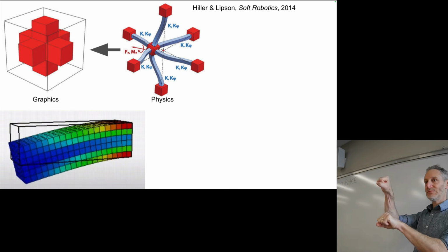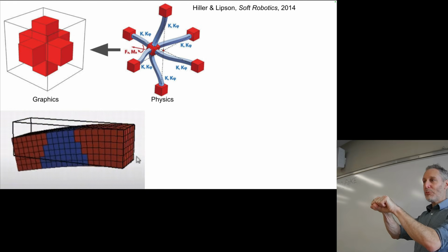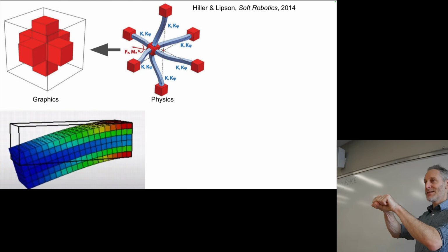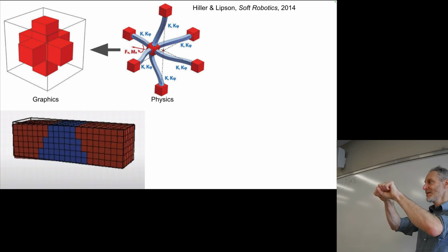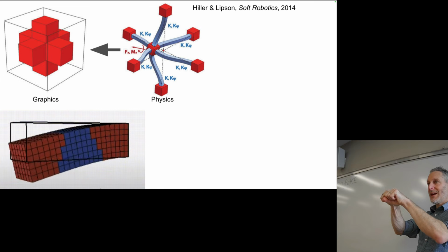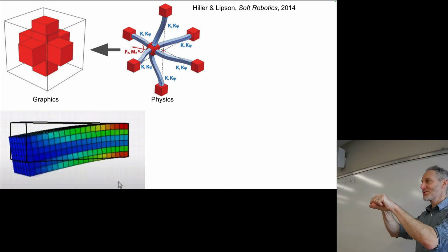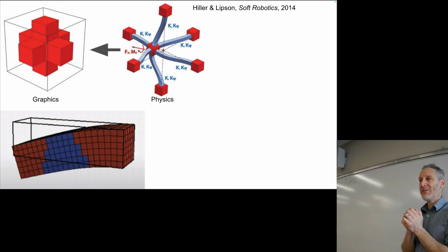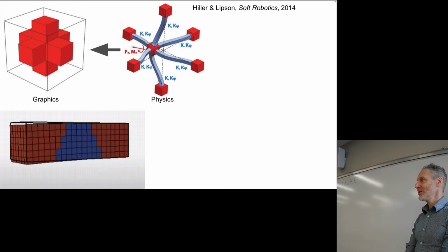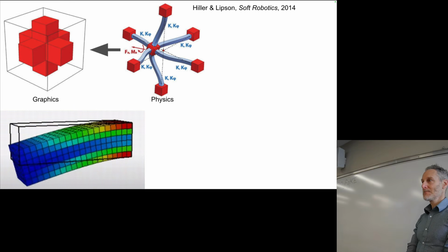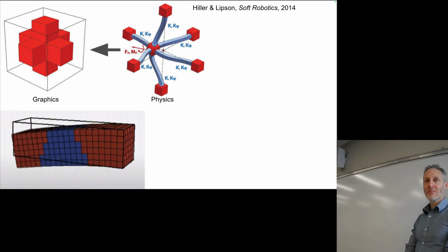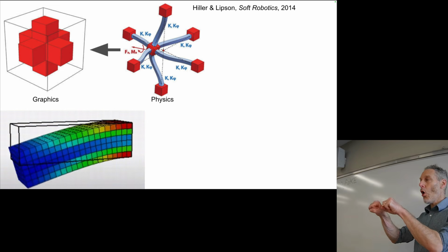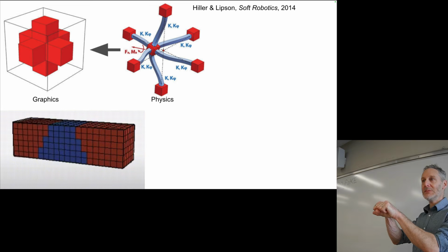and this. Yeah? Okay. K sub phi represents the 3 ways that the 2 ends of the beam can rotate relative to one another. This, and this. And those 3 are yaw, pitch, and roll, and I can never get them straight which one they are. So if all 6 of these numbers is very high, what is that beam's behavior? It resists all of those relative motions. It's a steel beam, right?